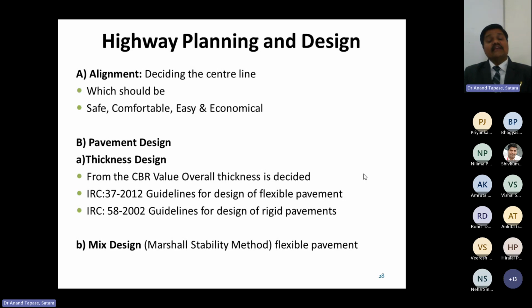The first one is the thickness design. That is the point we are going to discuss in detail today. And the second one is the mix design. Mix design is related to the experimental work that we carry out using the Marshall method. And the thickness design is restricted by the guidelines proposed by the Indian Roads Congress, for example, IRC 37 for the design of flexible pavement, and IRC 58 for the design of rigid pavements.